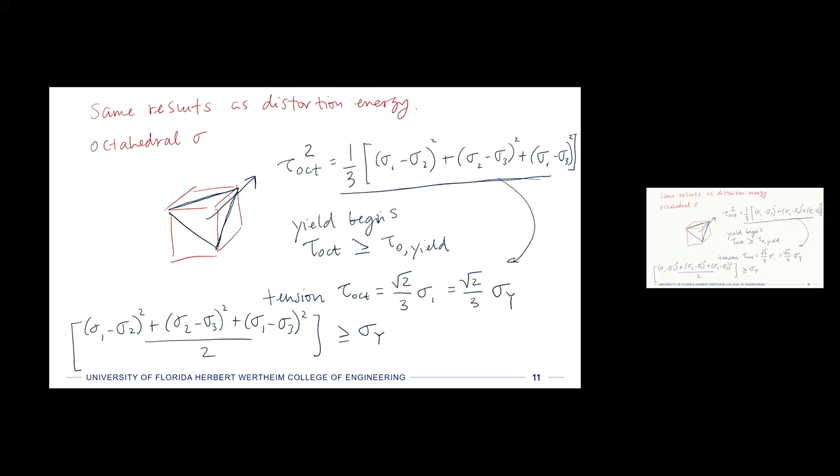Okay. So if we put the distortion energy theory and our Tresca, our max shear stress theory together in 2D, this can be a helpful map. So before, in a biaxial stress situation, right, we had our shear stress theory like this. But I told you that the data fell mostly outside of that. And so if we now plot the distortion energy theory with 2 stresses like this, then it is an ovoid that sort of hits the same vertices that the outside shape has.